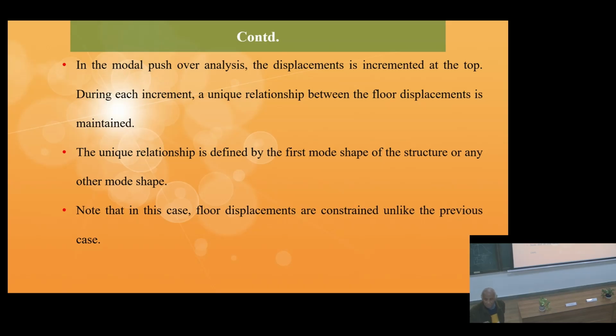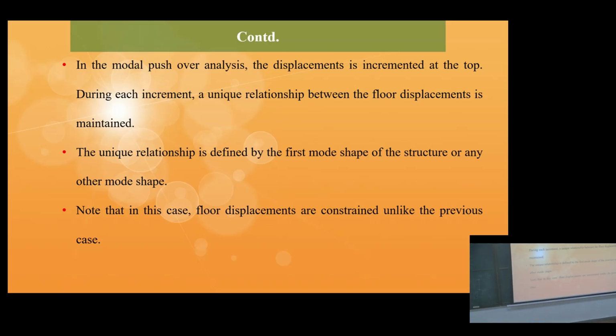It is different from ordinary pushover analysis, where I am giving only a top displacement, without any relationship with the other floors' movements. The unique relationship is defined by the first mode shape of the structure, or any other mode shape it could be, as I told you before.